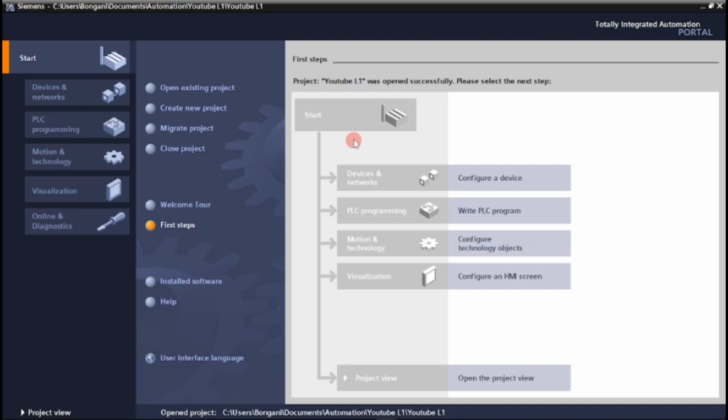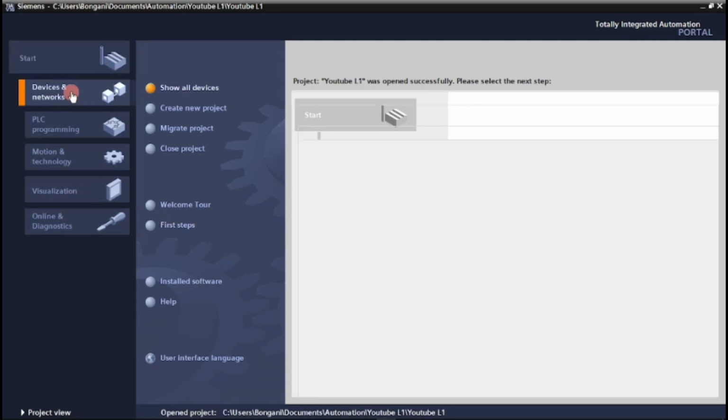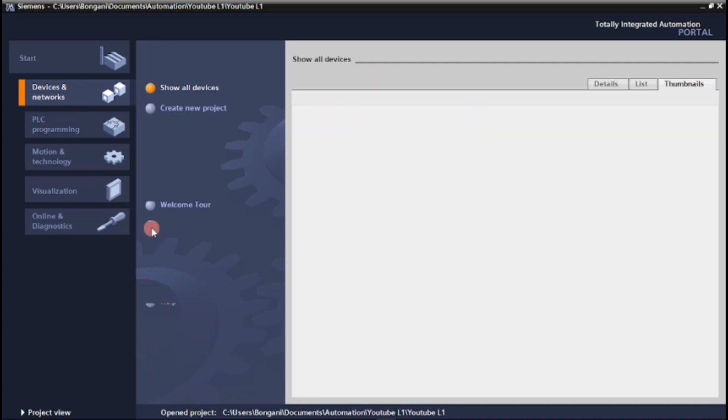This window you can also access on the top left, just below the start. It's the same thing. Right here, PLC program, configure, is the same thing as on the other side. You can do it in both ways, as I'm doing right now. Just go and click the start first and then add a new device, which is the same thing as when you go to configure.